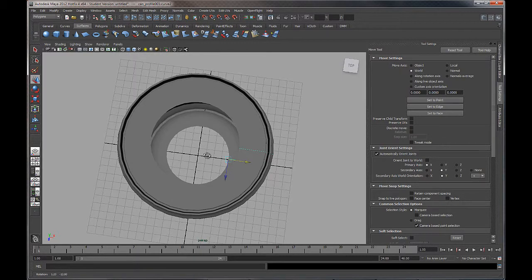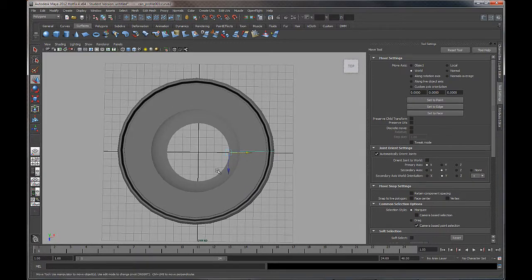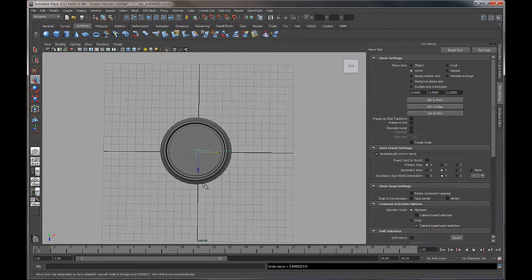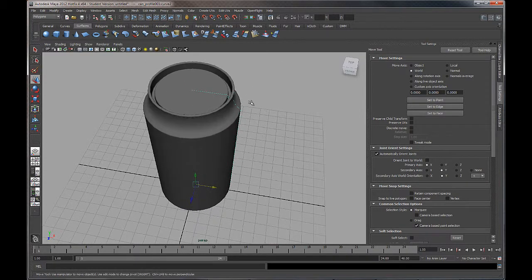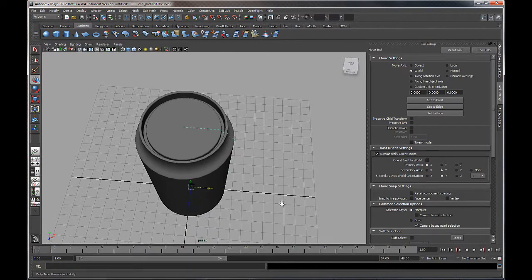So these holes that are formed, essentially, the reason why I set the file up for you guys is so that we wouldn't end up with any holes at the top of the can or at the bottom of the can like this. So I'm just going to undo here so I can close that back up again. It's important when you're doing a revolve function like this that the ends of the curves have to be smack bang in the middle of where the revolve axis is. Okay, otherwise you end up with holes or overlaps.